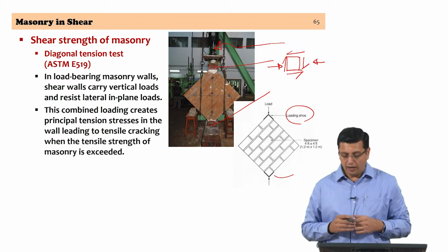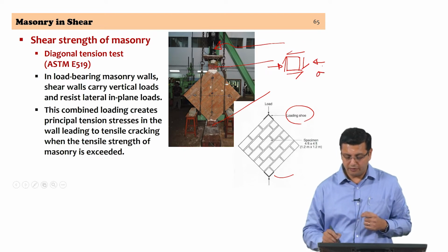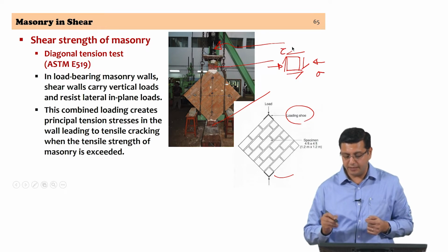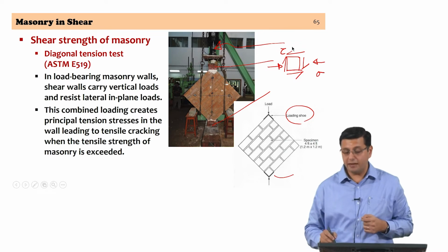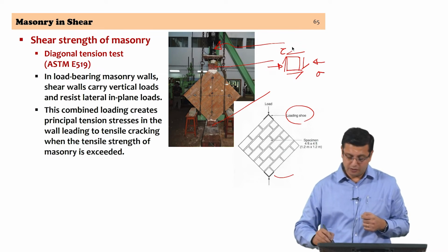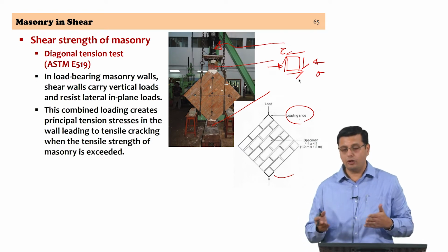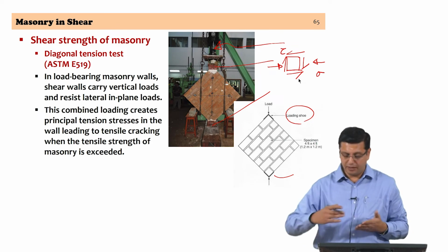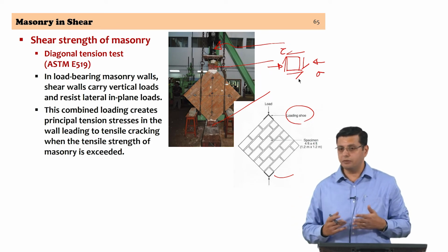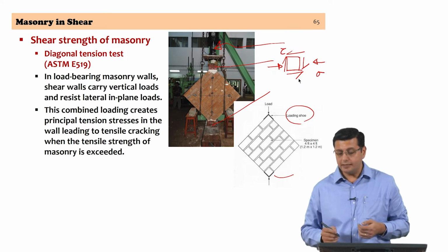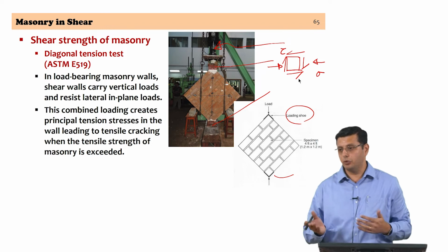Under this sort of situation where you have normal stresses and shear stresses acting on the material, you are interested in examining the principal stresses. If you consider a state of pure shear stress, then your principal stresses can be considered on a 45-degree rotated plane, but depending on the magnitude of the normal stresses, you know that the principal stress direction would change.